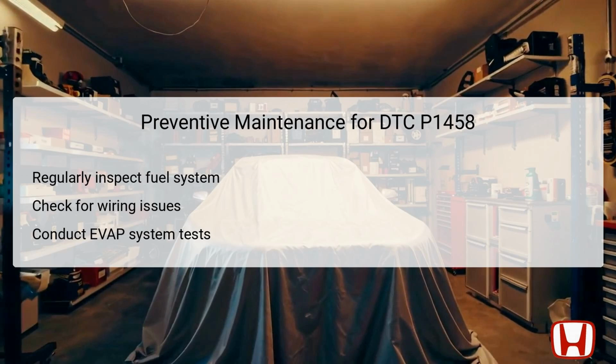It's also prudent to conduct periodic tests of the evap system, which can uncover issues related to pressure regulation that might not be apparent during everyday driving. Keeping the fuel system clean and ensuring connections are secured can extend the lifespan of your components and enhance vehicle performance. This proactive approach minimizes the likelihood of future diagnostic trouble codes and keeps the emissions system functioning optimally.